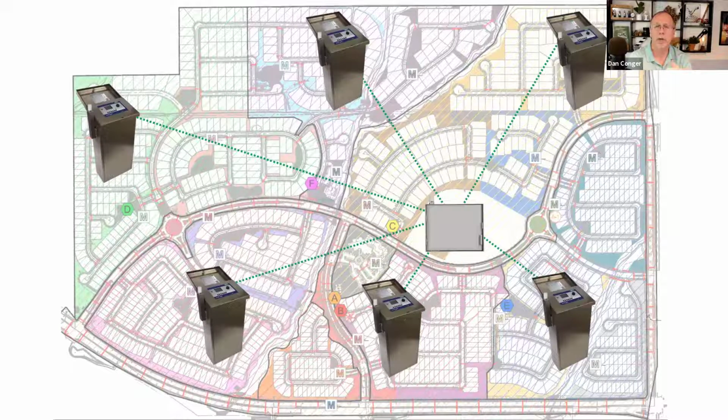So to manage it remotely, they needed communication methods. The original hardware they had planned on was to have each controller have an Ethernet radio in there and connect that to a radio hub. And then that radio hub would connect to the internet. So they'd be sharing an internet connection via radio for those multiple controllers.